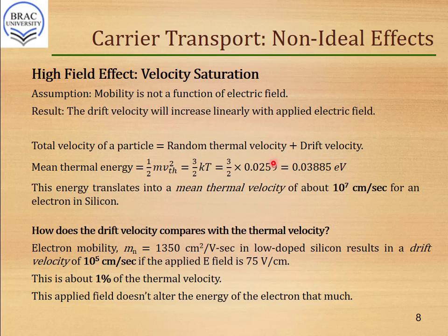If there is no electric field, the electrons are moving around in the silicon slab in a very non-uniform fashion. When we start to apply electric field, the energy of these electrons starts to increase. Okay, so they keep increasing as you apply more and more electric field. You can say that there is 75 volt per centimeter. So if the energy increases, they start moving with a greater velocity, and as the energy is increasing higher and higher, the collision between the electrons also increases.